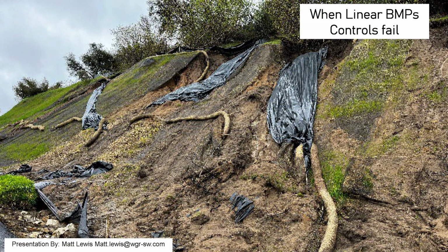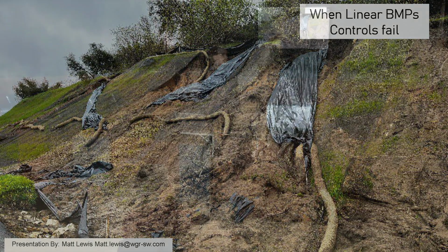And you can actually see that they did key in. It's kind of hard to tell in that second channel there, but they did key in their silt fence. They actually had fiber roll on the top of the slope. And I think personally, my opinion on this is that the slope is too steep for the distance. They only had one coming right down the middle.